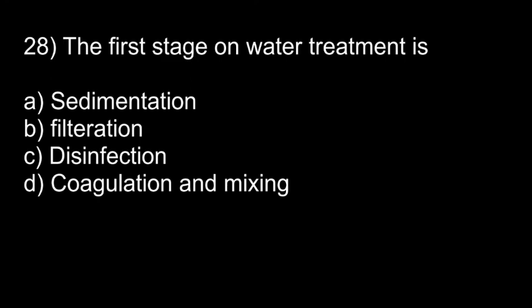The third step is coagulation. Sedimentation aided with coagulation: certain chemical compounds called coagulants are added to water. They absorb colloidal impurities and form flocculant precipitate called floc. These flocs are settled down due to gravity. Coagulation is necessary when turbidity is greater than 40 to 45 parts per million. And important coagulants are alum or aluminum sulfate, copperas or ferrous sulfate, etc.